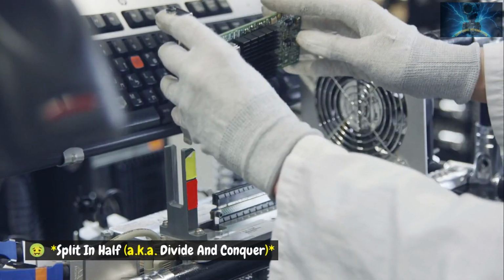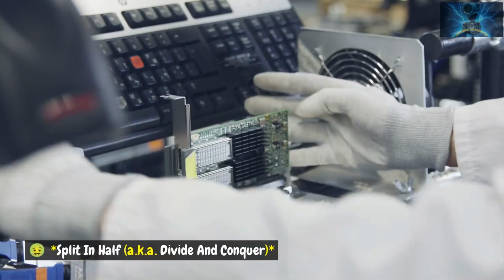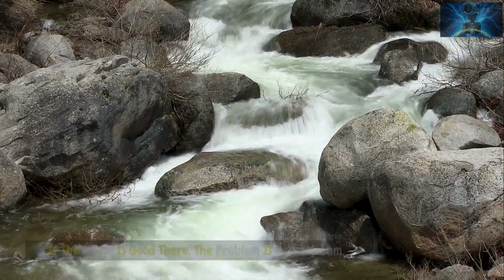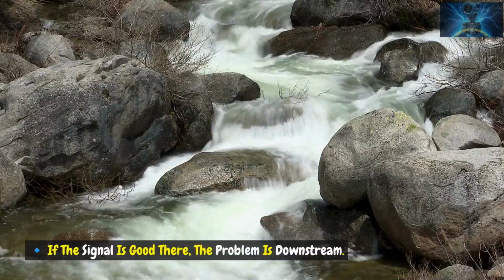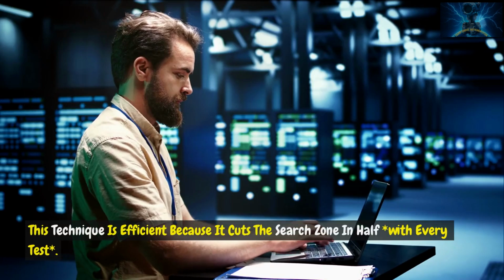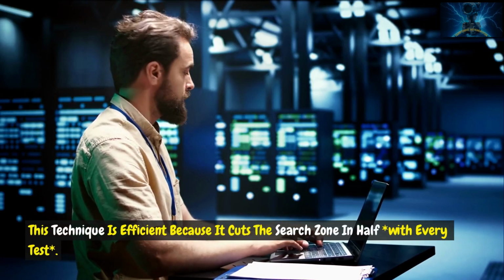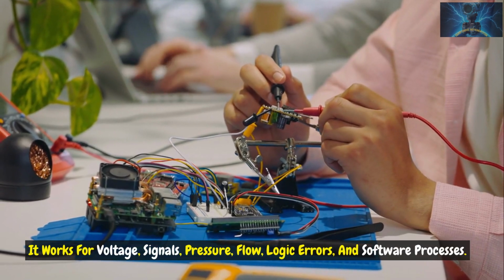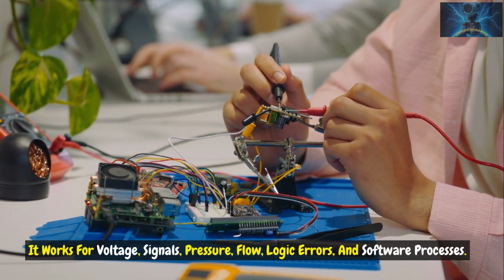Split in half, aka divide and conquer. If a system spans multiple devices or segments, test the midpoint. If the signal is good there, the problem is downstream. If the signal is bad, the problem is upstream. This technique is efficient because it cuts the search zone in half with every test. It works for voltage, signals, pressure, flow, logic errors, and software processes.